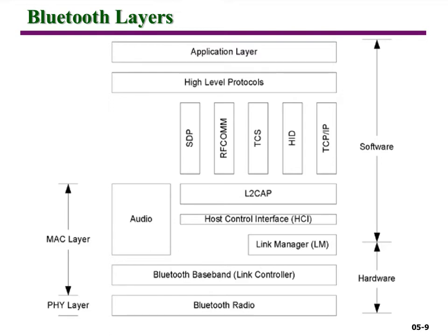So technically at every transmission you can switch from one frequency to another. Okay? Of course the hopping itself is random. And we said that the hopping uses fast FHSS, frequency hopping spread spectrum, and in the physical layer we use GFSK or Gaussian frequency shift keying as one modulation scheme.